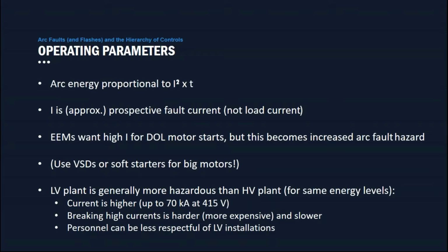And a little tip there for the EEMs: if you want to start big motors, have a think about soft starters or variable speed drives. It's a much safer way to go about it.